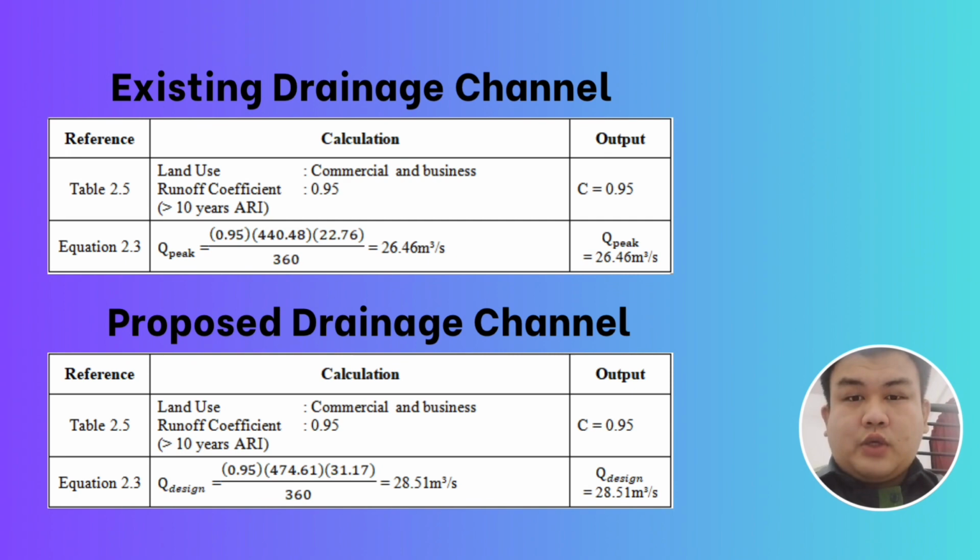In this slide, I would like to talk about the peak flow for the existing and proposed drainage channel. For the existing drainage channel, we get the runoff coefficient C from table 2.5 is 0.95. So we calculate the discharge from equation 2.3, and we get 26.46 meter cube per second.